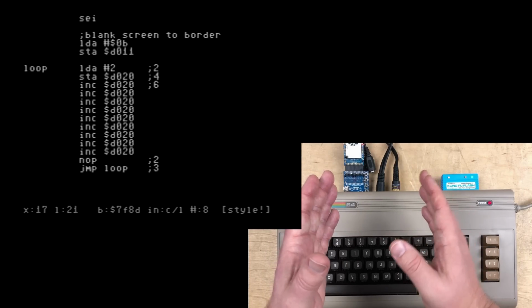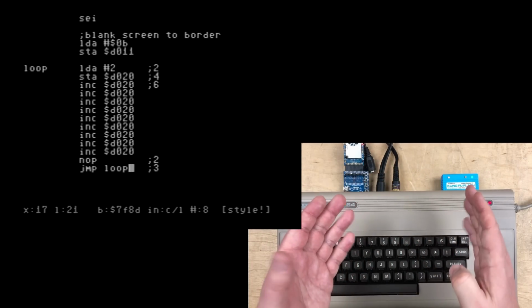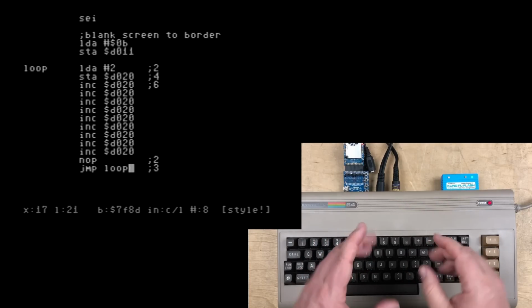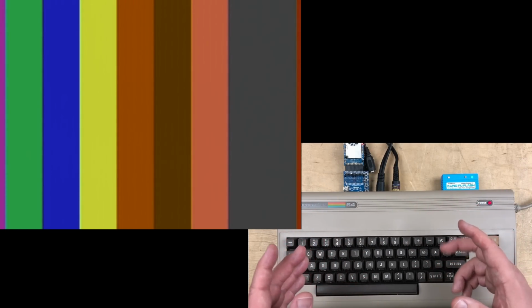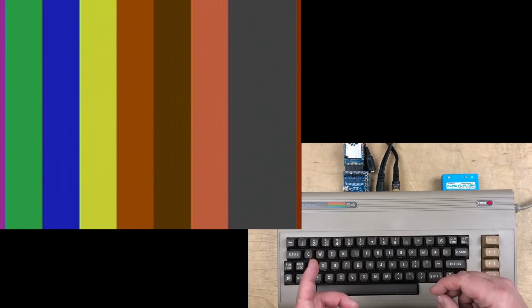So the background register is being changed at precisely the right intervals that all lines up as if we have these vertical columns down the screen. And again, this is our one giant border color pixel, but you see that is a misnomer. You might think, wow, it's only one register, but look at this display we're creating with it. And that's the concept of this on-the-fly programming, racing the beam, as it's called in the Atari 2600 circles. Well, the Commodore 64 is very capable of doing that too.